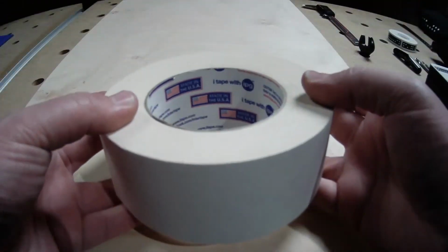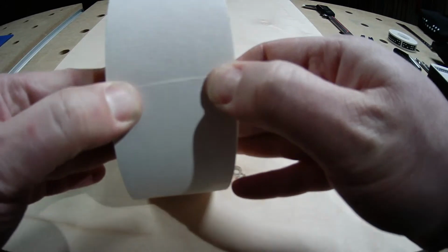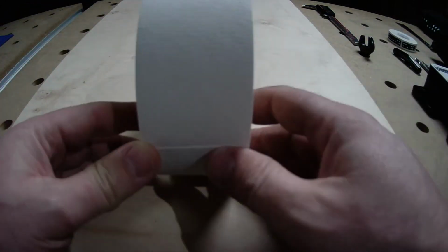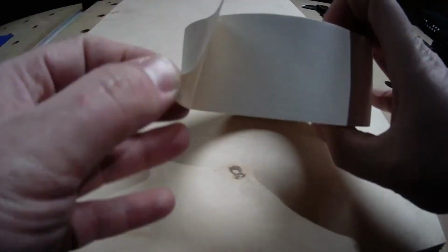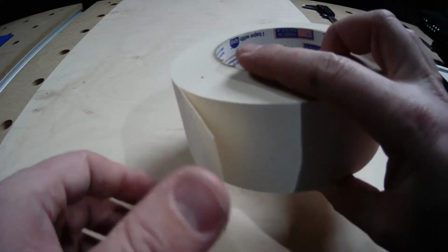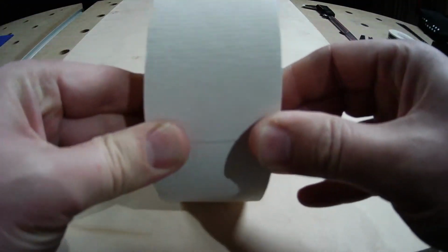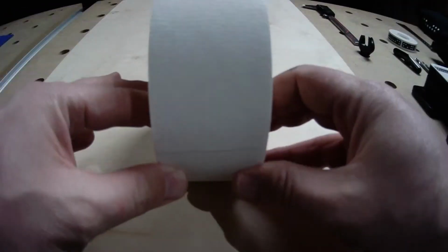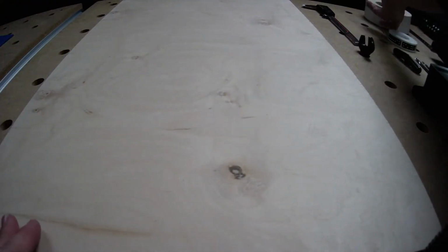So this is double-sided tape. And we actually sell this on the Shaper store now, but this is a brand of tape that we have been using for years in the Shaper workshop. It's really thin. You can see if I just kind of pull that off. It's very, very thin. It's a paper substrate instead of the foam style stuff that's like carpet tape or VHB. That's not going to work for machining, but this double-sided tape is amazing, and you should definitely pick a roll up from the store.